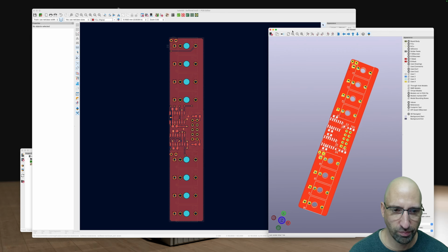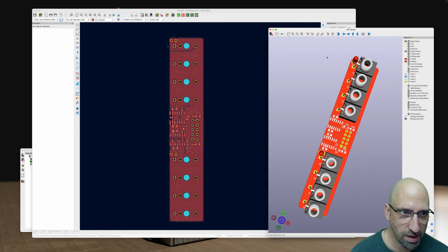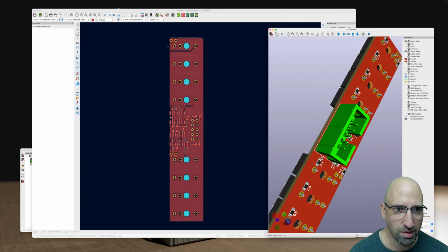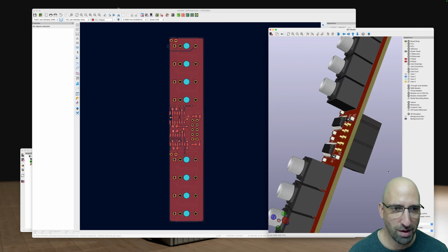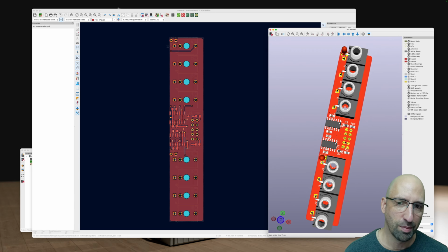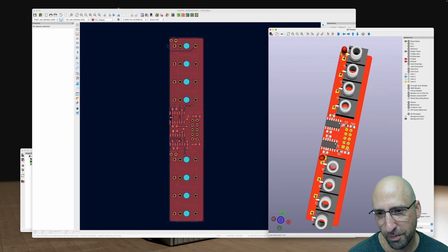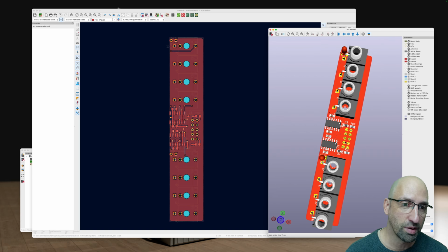And yeah, I think for now, I'm going to call it there and say good luck and do your best at laying out your board. Controls first, power next, power planes, and then figure out your actual component layout.